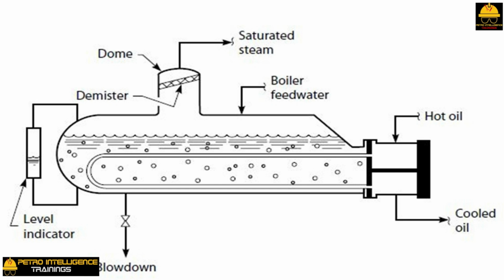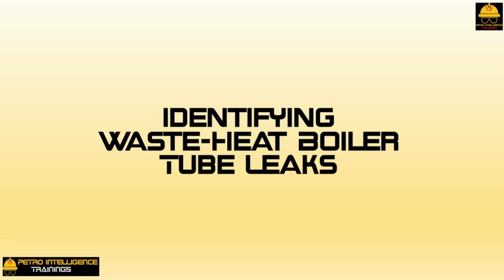Of course, if the steam from the kettle will be used to reboil some nearby column, entrainment is not a major problem. If the steam is going into superheater tubes, however, serious entrainment will lead to solid deposits inside the superheater tubes, and this may cause these tubes to overheat and fail. Fouling of turbine blades would also result.